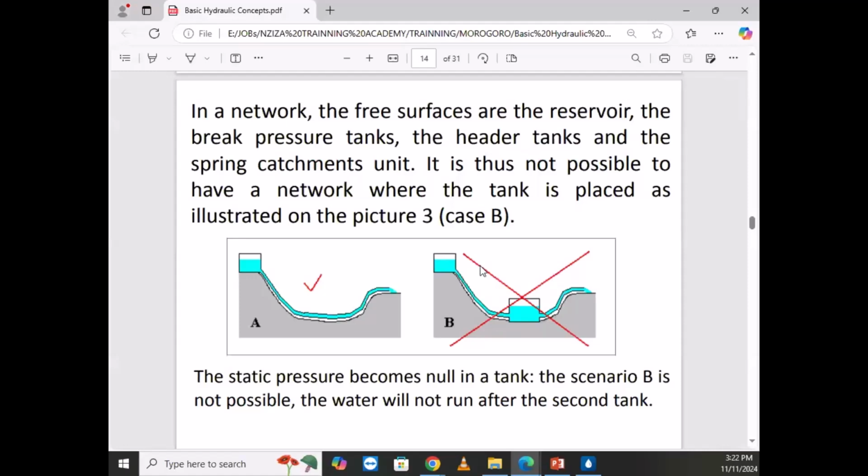And this case, I think it will not happen to you. Some people locate the pump just down the hill, and the hill stops the water from reaching, according to the pressures that you saw. If you locate your tank just down those hills, the water cannot go beyond this level unless you add a pump. Yes?